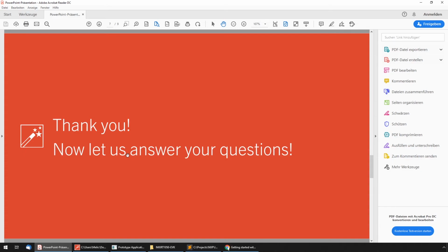Yeah, so rendering a TrueType font. In fact, the default behavior of Embedded Wizard is really to generate the glyphs, so the pre-rendered bitmap information of a font, into the generated source code. However, it could be that you have Chinese, for example, as an input mechanism, or a Chinese language, and you need to use an input from your customers in Chinese. That would require that you take care of all the different characters available inside the Chinese language. As you probably know, there are tons of characters in that character set, and if you would pre-generate every glyph for Chinese, this would simply explode your flash probably.